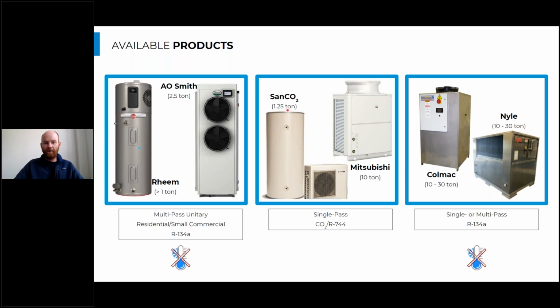This is a 1.25 ton unit. So we could have done what we did at HopeWorks, which was a handful of clustered heat pump water heating systems, central systems. But for this size of the building, we would have had at least 30 of those systems, which would be tons of maintenance points for those maintenance personnel. And so we decided not to do that.